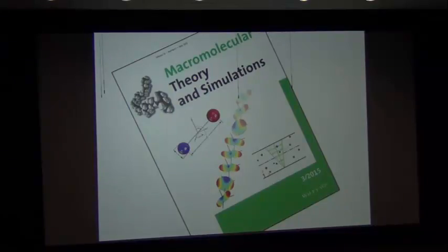This fascinated me. We've always used rheology to learn about molecular orientation. That's been the main access to what the molecules are doing, this sort of indirect business that I'm showing you here. But it never occurred to us that there were parts of that orientation distribution that were not accessible at all to us rheologically. But when you try to calculate the whole orientation distribution function, then you have to do even more work than I've shown you today, and of course, specifically, you have to calculate that fourth term that I mentioned in the orientation distribution function.